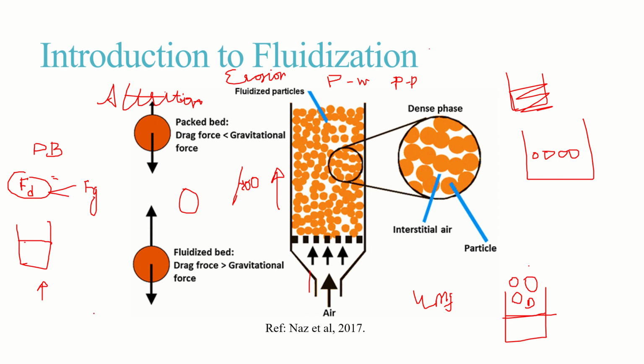Also, think about it, here the solids keep on moving. In catalytic reactions, once the catalyst is spent or used up, we need to regenerate it, or I mean we need to recycle those catalysts, right? For that we need to move the catalyst and recycle it separately. If we are dealing with the packed bed, it would be very difficult to operate at the industrial scale. The particles would be over here, and we need to remove them, recycle them and regenerate them. It is quite a hectic task.